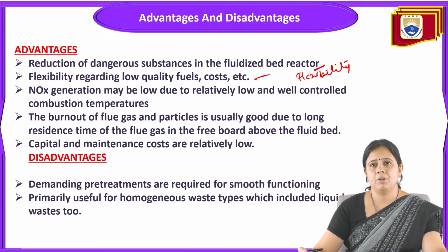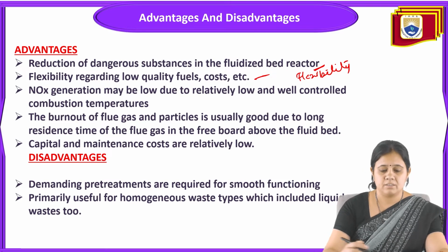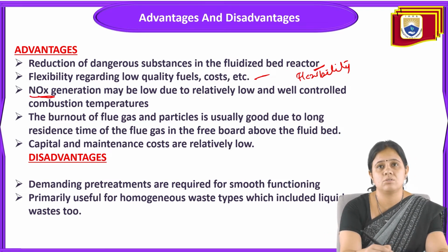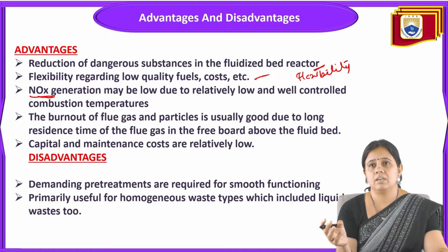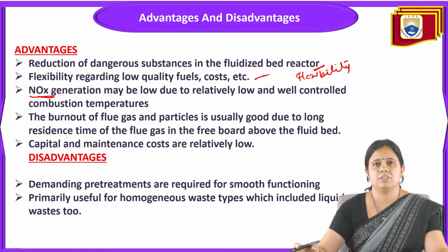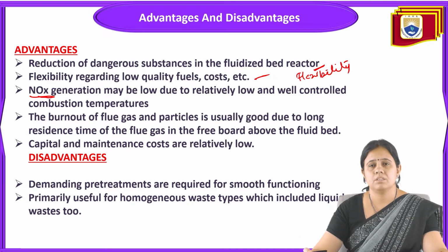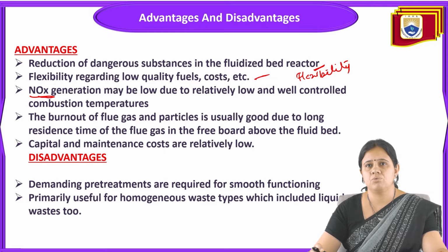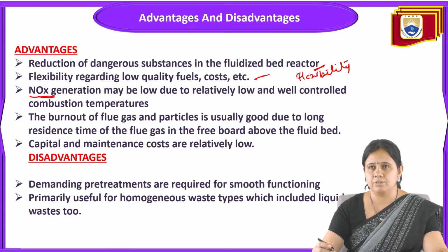NOx generation may be low due to the relatively low and well controlled combustion chamber. This NOx generation is also low because of the well controlled combustion chambers. The burnout of flue gas and particles is usually good due to the long residence time of the flue gas in the freeboard above the fluid bed.